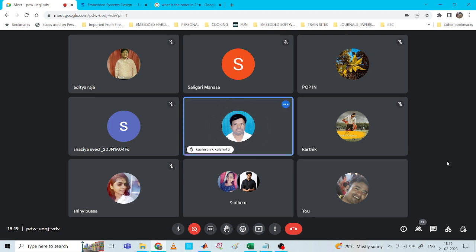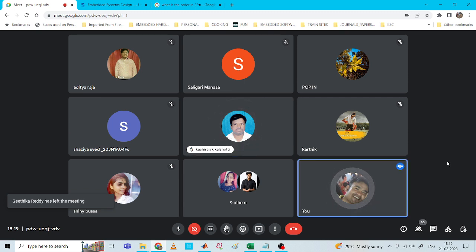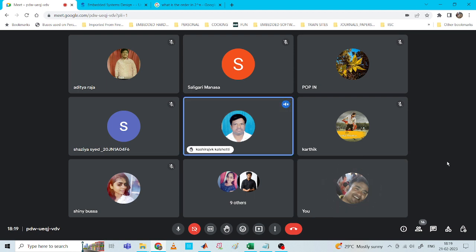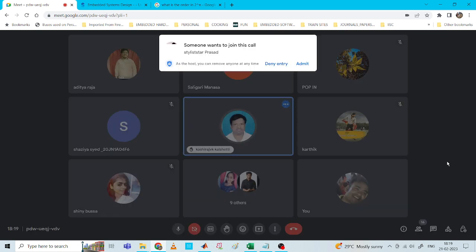Okay, sir. And one more question, sir, regarding this delta sigma. Actually, the way you should take the resolution is 5 divided by 2 to the power 8 minus 1. So you have to take 2 raised to 8 minus 1, sir. Yeah, so it is 255. Okay, thank you, sir.